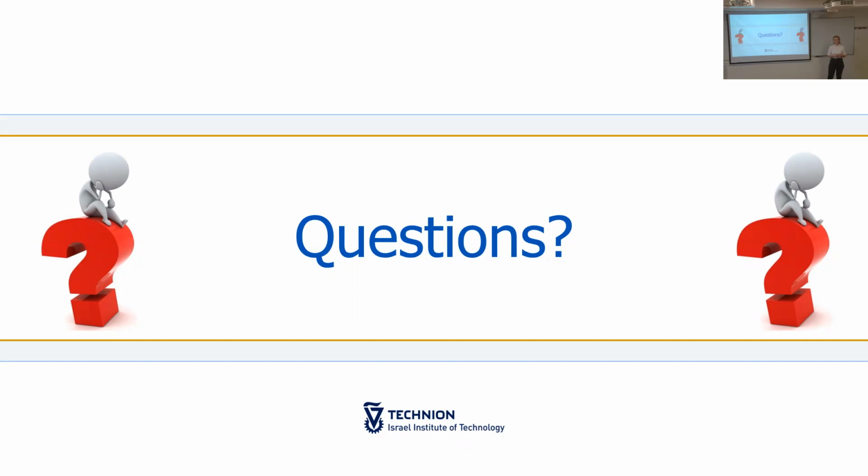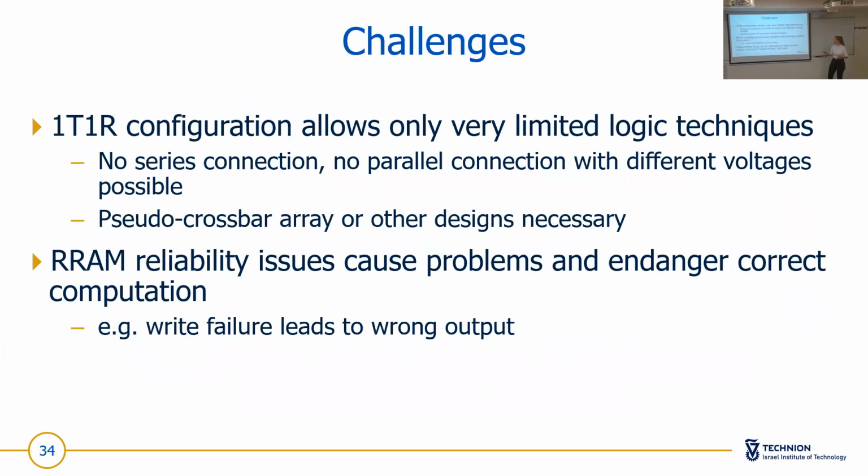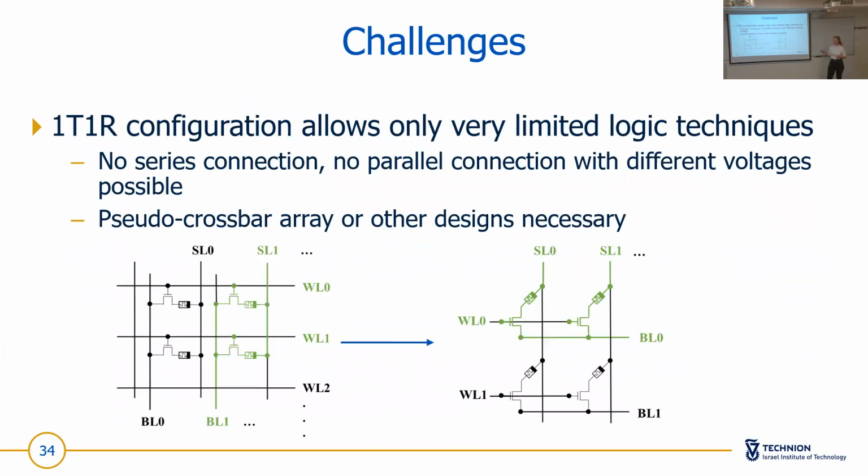So I guess the used 1T1R arrangement is very well scalable. So it is very common, very easy to manufacture, and you also avoid other sneak path currents because you really can only connect this one column, and the rest of the cells is completely untouched.